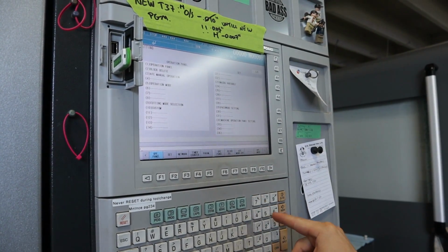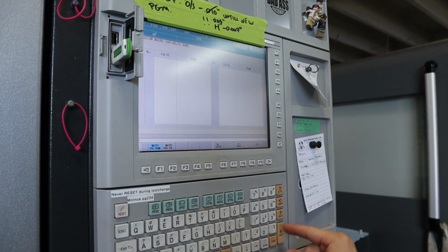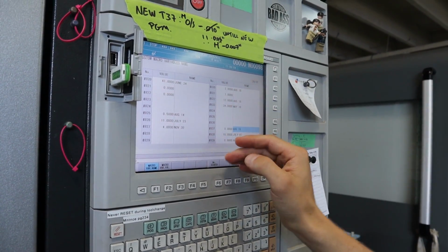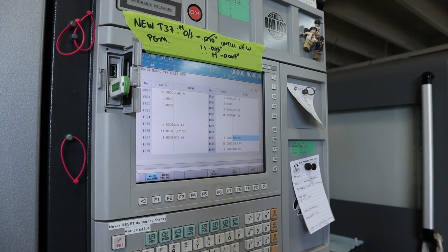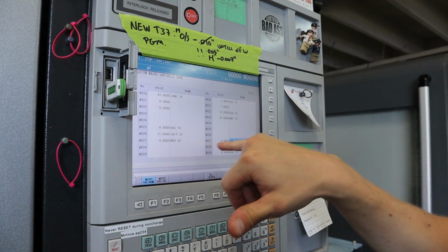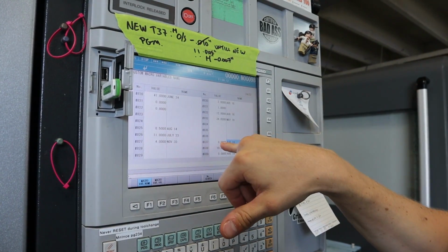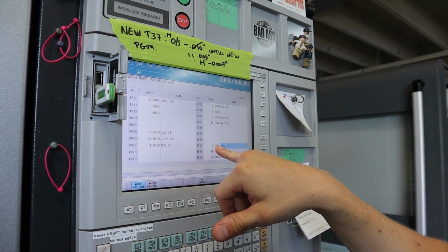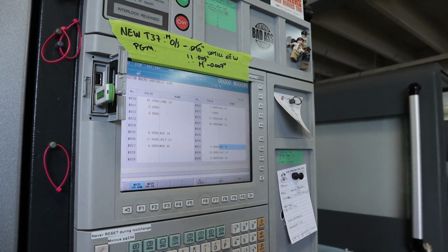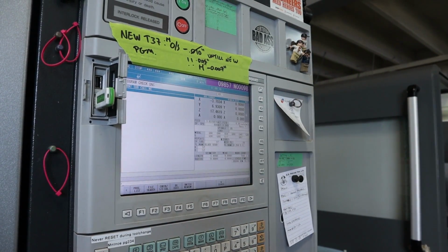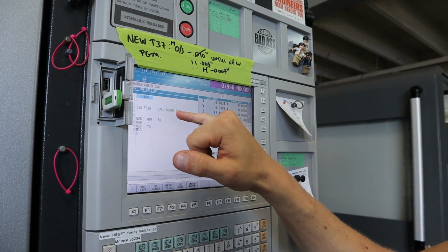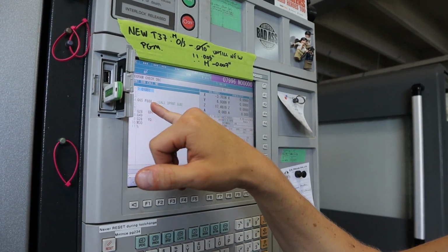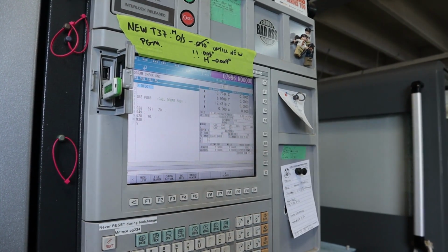And then if we go into 23, these are all my macro variables. I'm trying to dump all of those onto the USB stick. Some of the tools I just changed, tool 37, just changed today. Set the counter back to 0. And then go to the DNC side. Here is my DPrint program, which is just a subroutine call to G65 P888, so code 888.